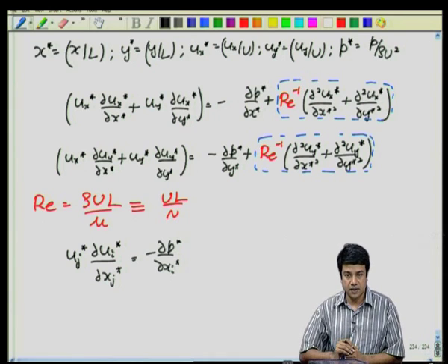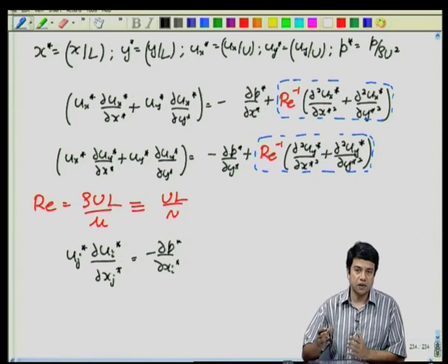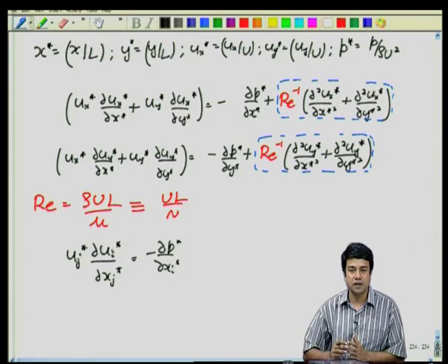In this particular case, for the flow around a flat plate, the pressure gradient turns out to be equal to 0, because far away the equations are inviscid and I just have a constant pressure everywhere. So, since the pressure gradient turns out to be equal to 0, I just find that u dot grad u is equal to 0.